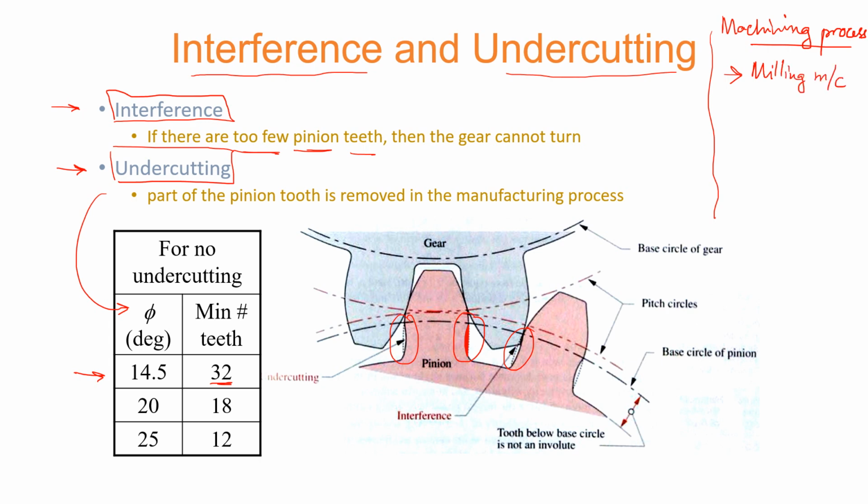There are different kinds of milling machines that can be used, but in a manual operation you have a dividing head mounted on the milling machine, and this dividing head specifies the type of tool engagement with the workpiece, which allows a special kind of gear profile to be machined.